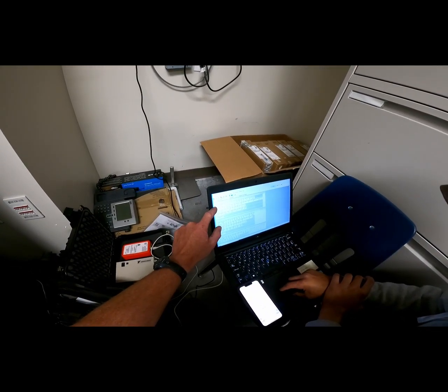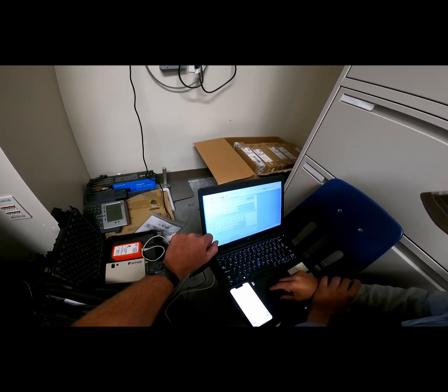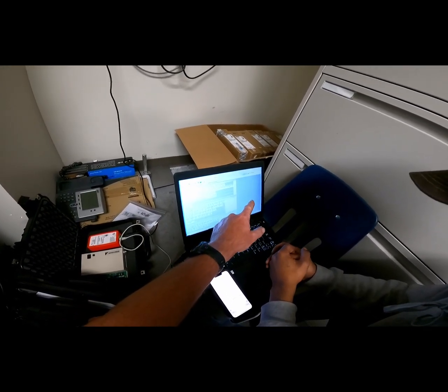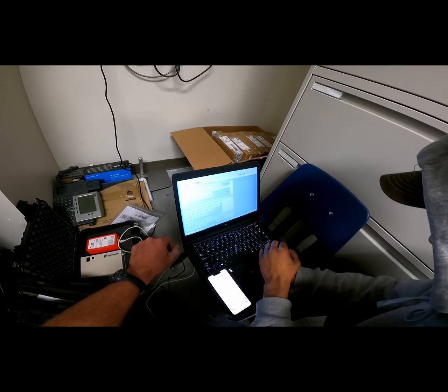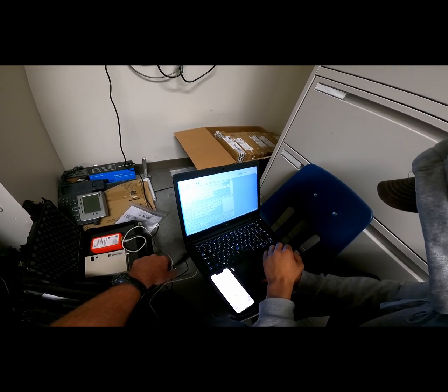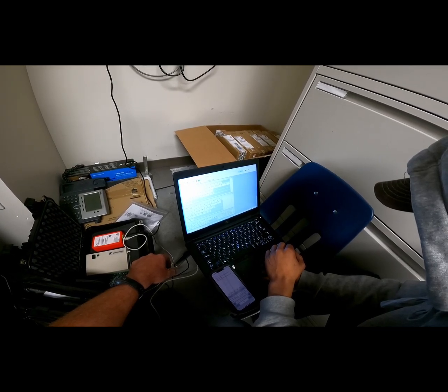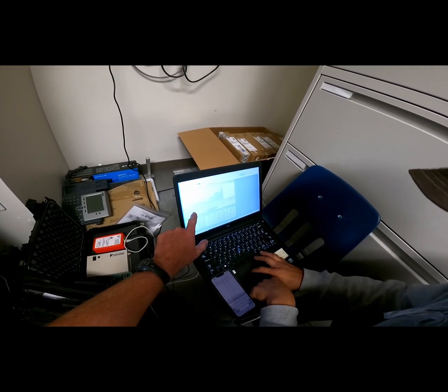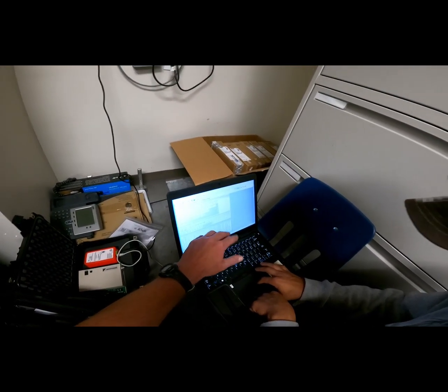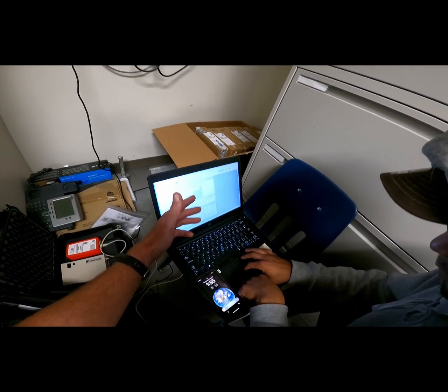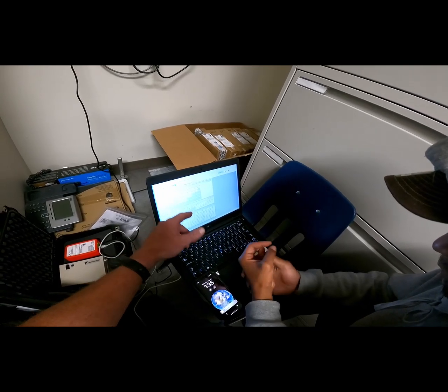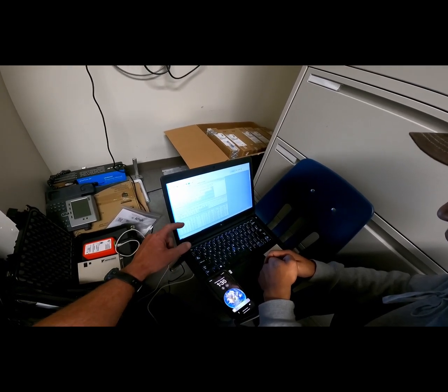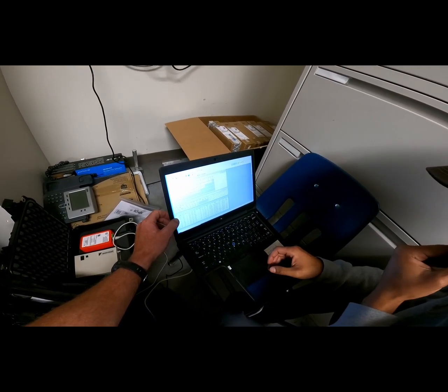This window here is your outdoor leader. See, it says OC. This is your outdoor follower unit that's tied to it. And grab the bar on the far right and scroll down. There you go. This here is your branch controller. It shows you the solenoid positions. So each one of those line sets that comes out of there has 3 solenoids on it that are allowing the refrigerant flow. And these 1s and 0s let you know whether they're open or closed. We'll get into that later. The bottom box is all your indoor units, and it shows you their addresses on the left.